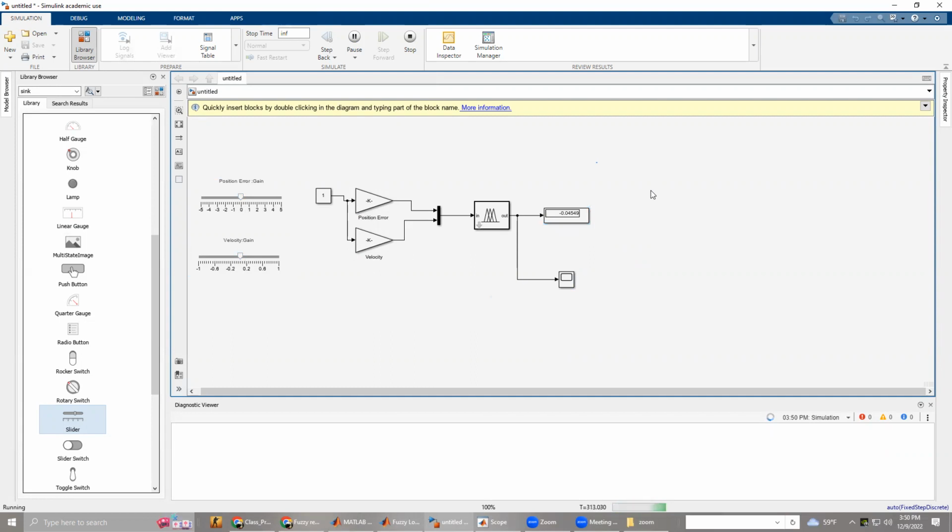Now we can explore some different cases, such as the robot is too far away and is doing nothing. The fuzzy system says that the robot should move closer. In any case where the robot is too far away, no matter the velocity of the robot, the fuzzy system will always decide that the robot should move closer. What changes is by how fast. As you can see, the output of the fuzzy system changes from around 4 to around 0.75 as we change the velocity.